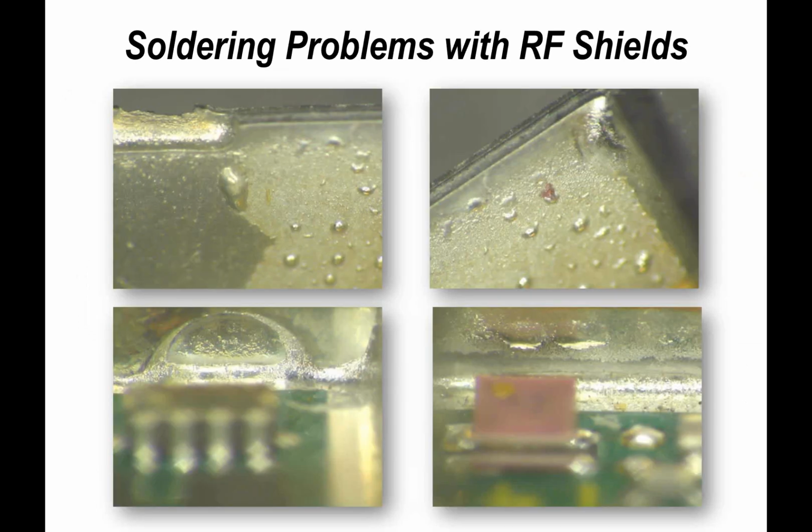Now, just one thing I wanted to chuck in, because I'd seen this just recently on some frames that I was soldering. These are some examples of slight de-wetting but more outgassing. One thing to bear in mind, that all tin surfaces are not necessarily going to solder really, really well and effectively. Yes, they should do, but also look for those surfaces outgassing.